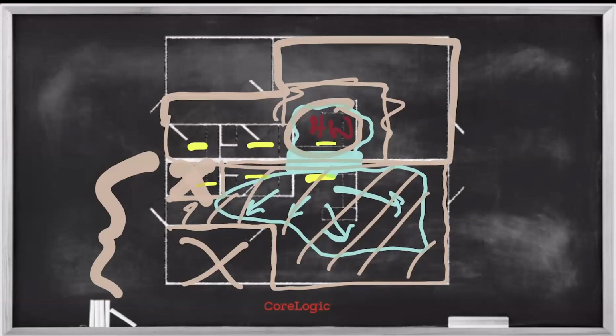All right. With class 4, what I typically interpret from the S500 is that if we are dealing with only trapped water that is hidden or that is absorbed only in low porosity materials, regardless of the percent area that is affected, I generally treat those as a class 4. And the predominant reason that I do that is because I want to produce very, very low humidity. Not necessarily a high volume of humidity control, but a very low humidity. And there's some good guidance in the S500 for how you establish that lower humidity, especially even with the dehumidifier sizing guidelines and the fact that desiccants become an option in my class 4 environments.